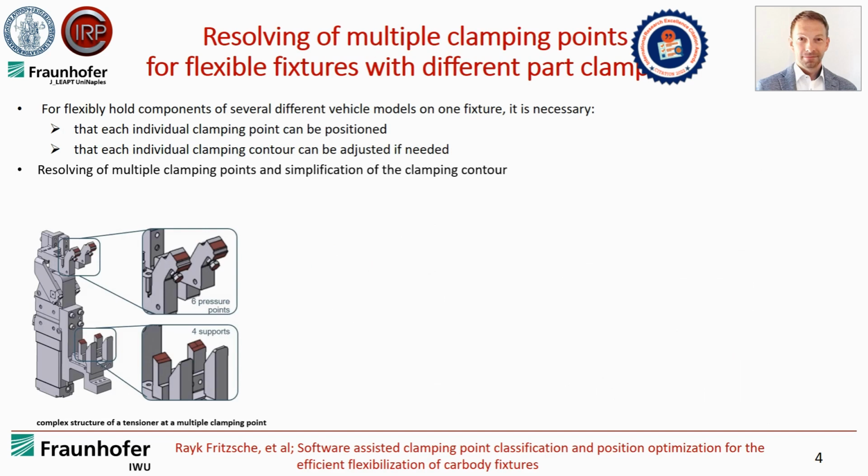To fix the components of several different vehicle models on one fixture, it is necessary that each clamping point can be positioned, and also that each individual clamping contour can be adjusted if needed. So we have to resolve such multiple clamping points, and we have to simplify the clamping contours if necessary.